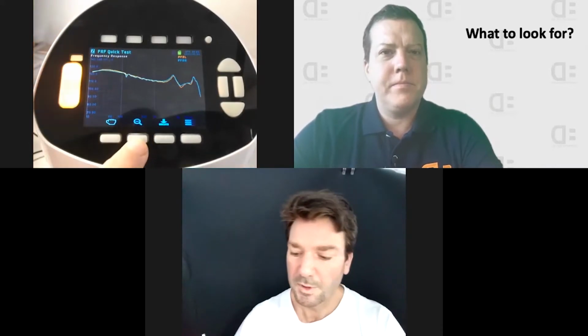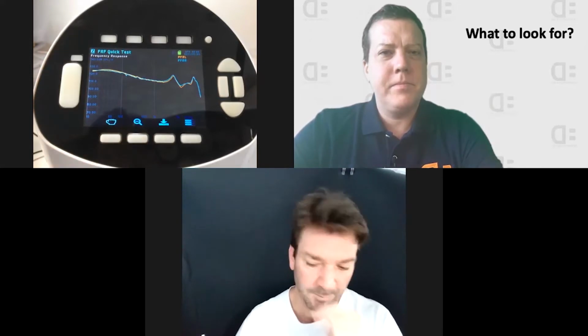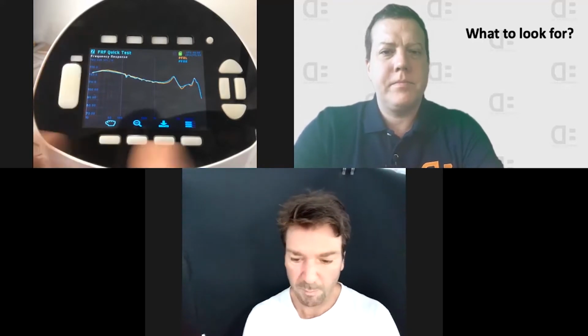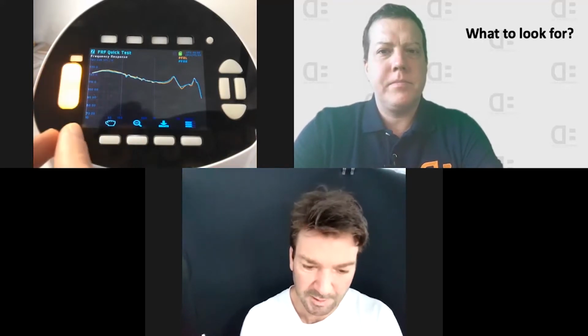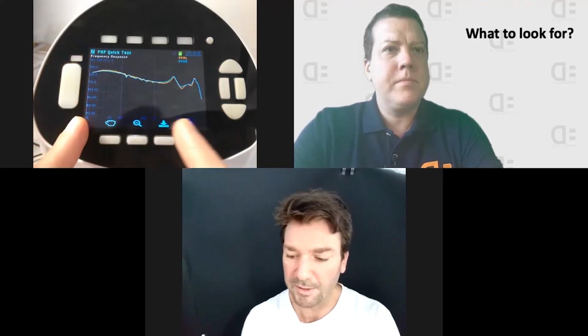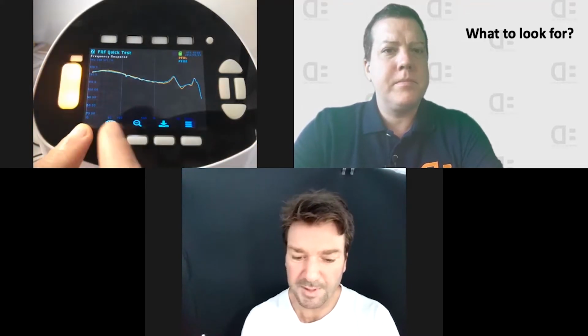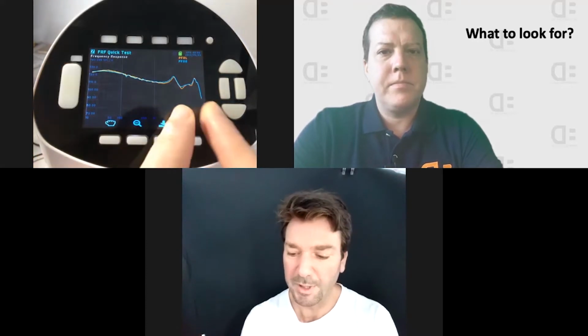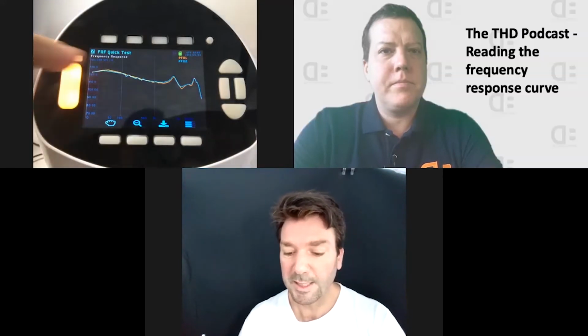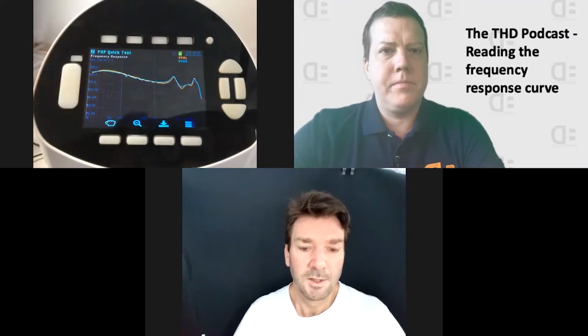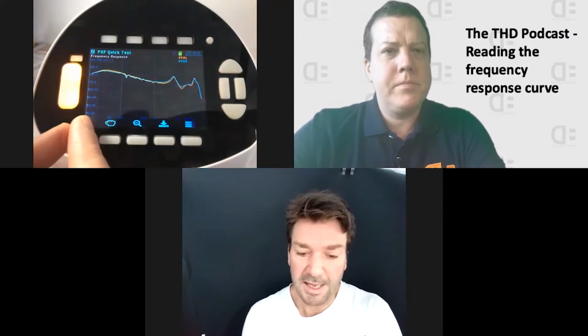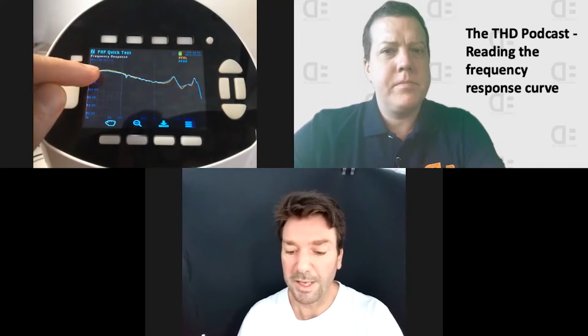Just like the curve that you just put up, this is going to be a fairly similar type of thing. It's an insert earphone. And when we look at the curve, you may already know this, but we'll just cover the basics. You have frequency on the x-axis along the bottom, starting at low frequencies, going to the mid frequencies in the middle, and high frequencies on the right-hand side. And then the y-axis shows us the SPL level, or how loud it is. So what the curve is showing us is, at any given frequency, what's the SPL output compared to the rest of the frequency curve.